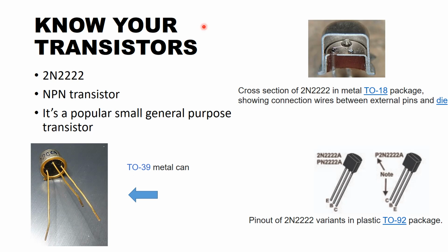So as you might have noticed in our previous video tutorials, we have used the transistors from the SPICE device library. There were hundreds of different transistors from different manufacturers, and that was the part number. We said we right click the model and see the SPICE model parameters. So when you build real circuits on a breadboard and then manufacture it on the PCB, you will often come across which transistor to choose from.